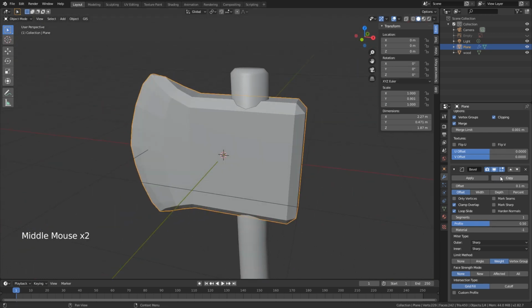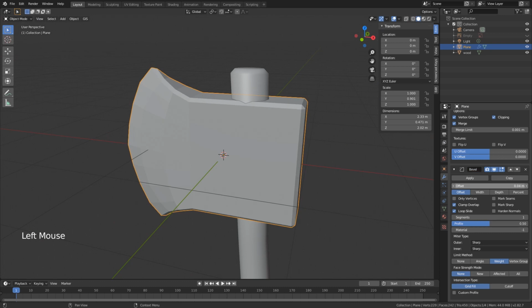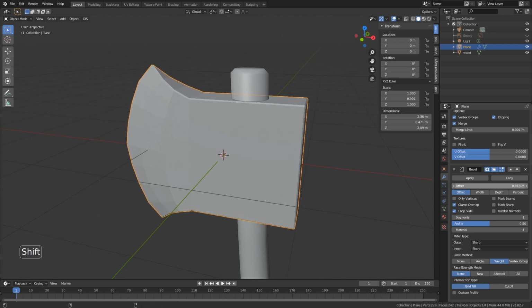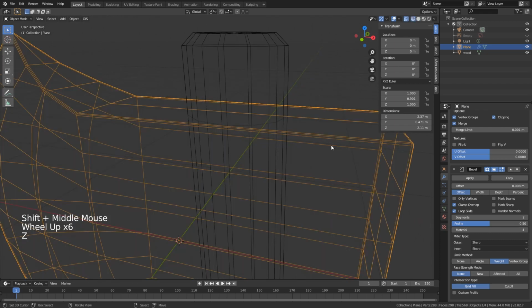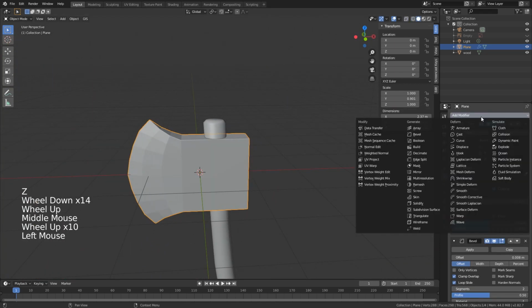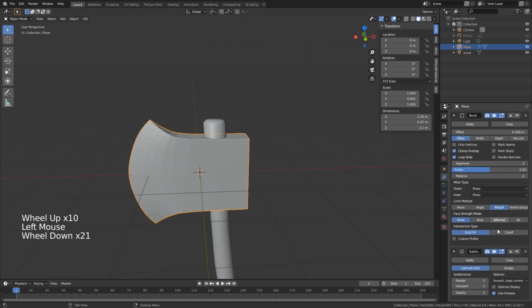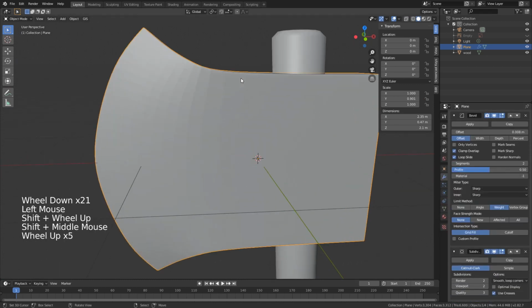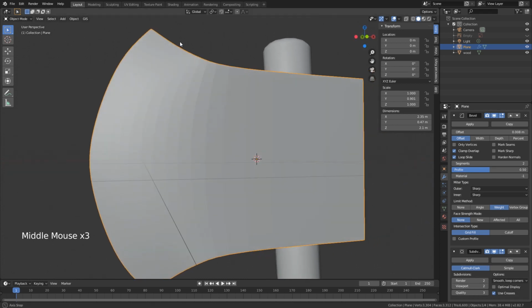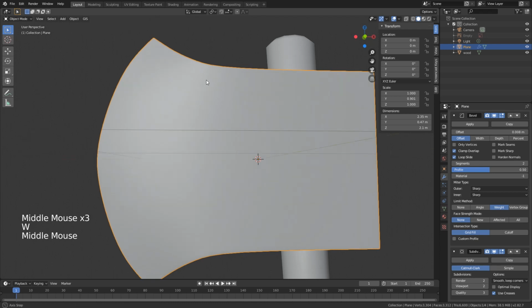Now in the bevel modifier, you can essentially change the offset a little bit so it's not that sharp. And then you can also change the segments, so you can put more segments or fewer segments in here. So you can literally see what we just did. We created this bevel. So now we can also create a nice subdivision surface to make everything a little bit more high resolution. And even though we have the viewport already at 2, we want to create a smooth shading so those little blocky details go away.